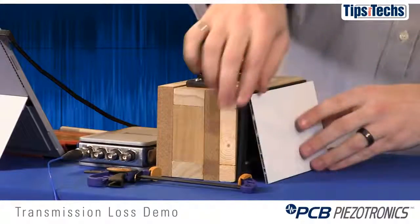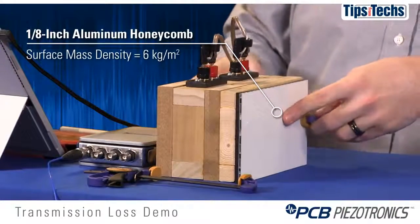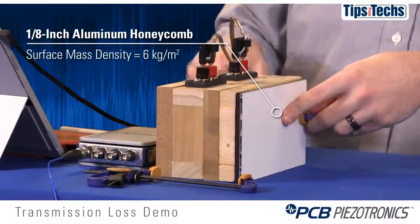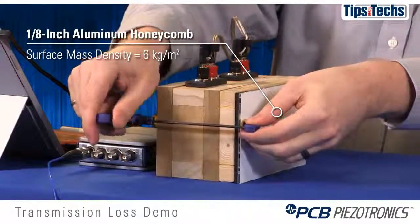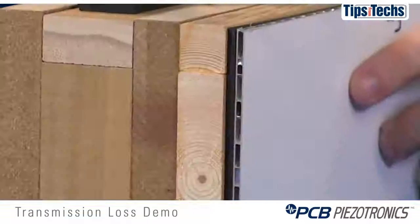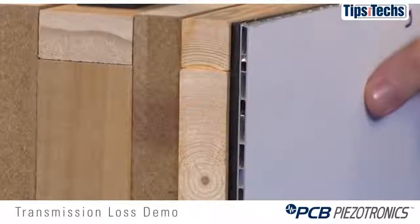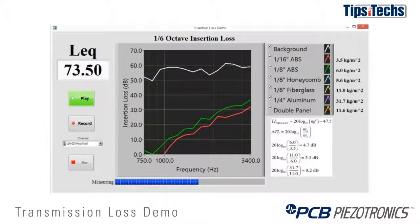Next, we'll try an aluminum honeycomb material. This is also 1/8 inch thick, and it's almost the same surface mass density as the last ABS plastic that we used. But it's a double panel design with little air gaps in the honeycomb lattice. So the mass law would tell us that we should get the same insertion loss for the honeycomb material that we got for the 1/8 inch ABS.